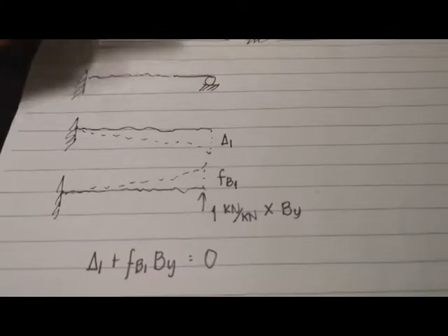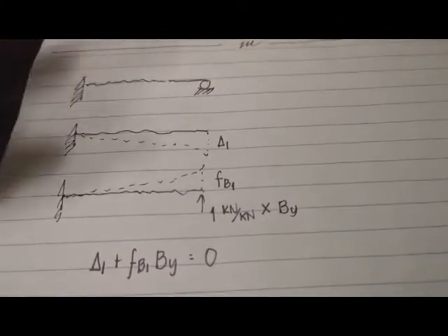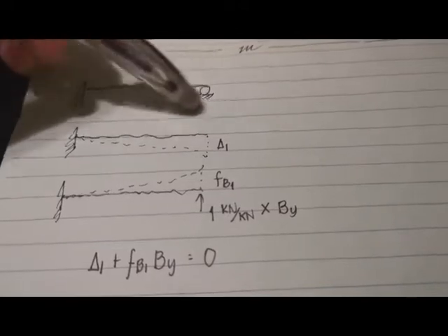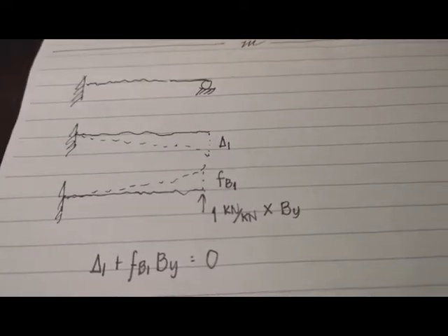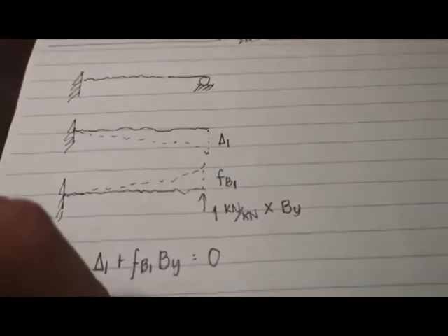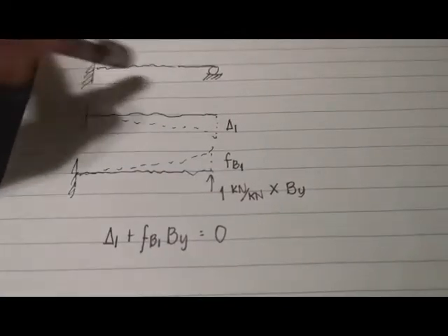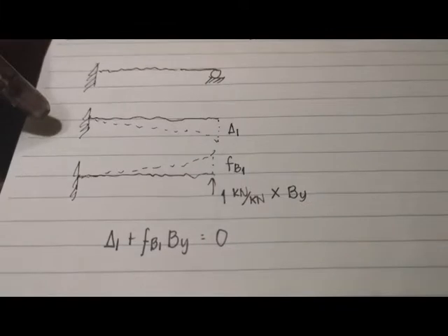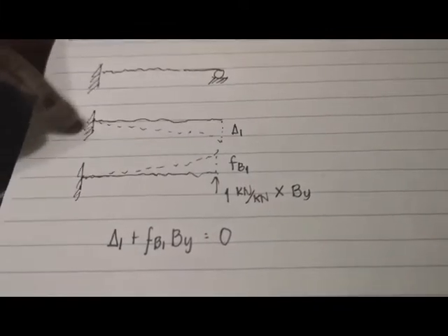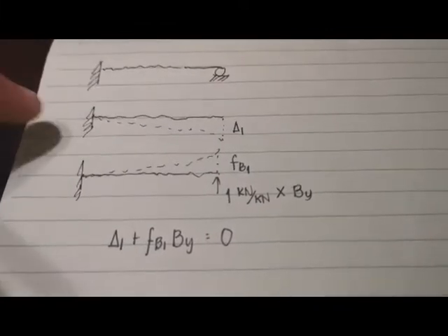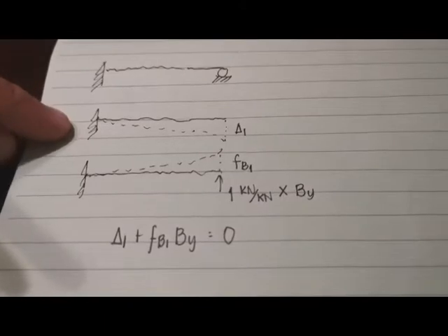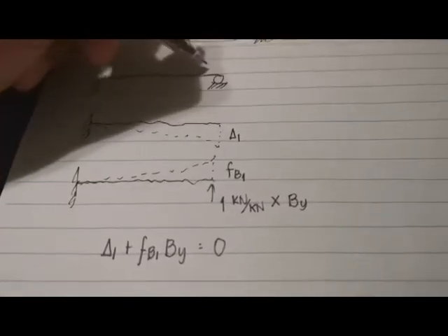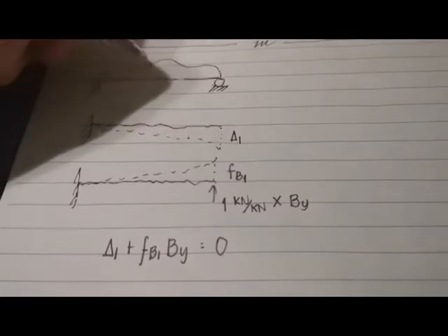So in this case, for the sake of the discussion, I'm just going to remove the support on the right. So now, because I removed this, this is what I made as the redundant. So this is now the look of the beam. It's already a fixed support. So assuming that this is my original load.